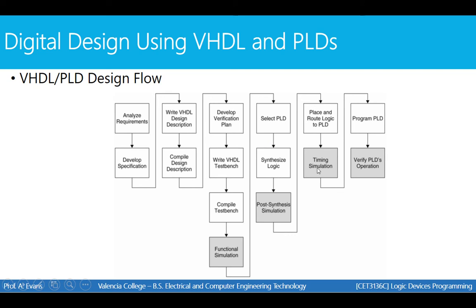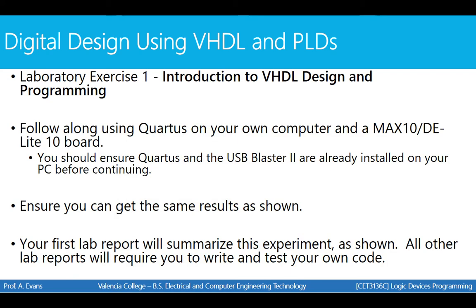You can choose to do a timing simulation at that point, so these simulations are things you can do along the way. But after Quartus has synthesized your logic, Quartus will do the place and route logic to the PLD, and then Quartus will give you a file that you can use to program your PLD. Once you do that, you actually investigate whether your code works on the PLD itself. And that's sort of an overview of the design flow that we're going to use whenever we create an architecture for a PLD. And that's just a quick introduction to VHDL.